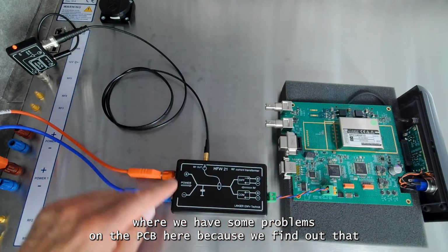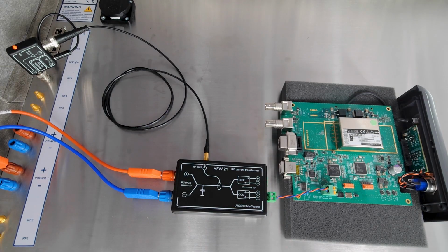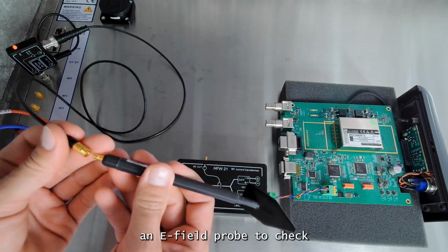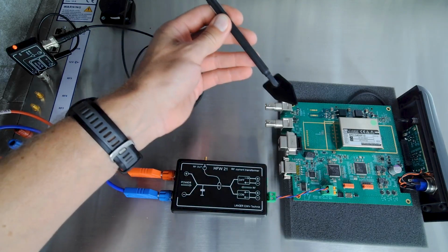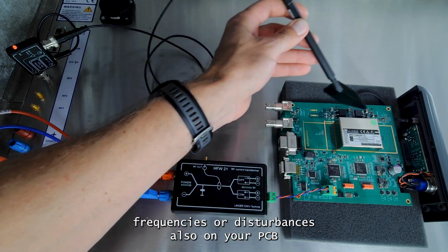Because we find out in these measurements or in the antenna measurements that we have a problem in a specific frequency range. And now we can use some near-field probes, for example this E-field probe, to check if you can find the same or similar frequencies or disturbances also on your PCB.